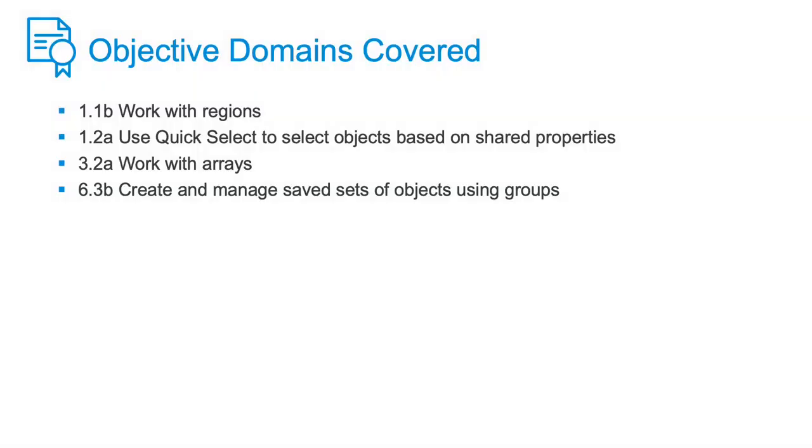We used the Region tool to create a spur gear. We also used the commands Polar Array, Group, and Quick Select. In addition, we did some Boolean operations like subtract and union. Boolean operations can be used with regions, solids, and surfaces.